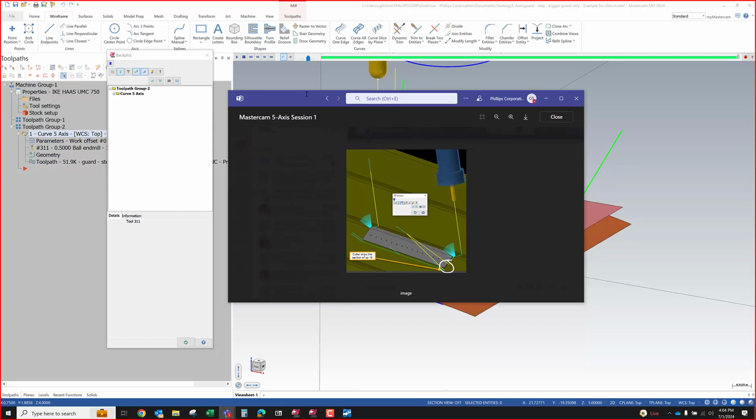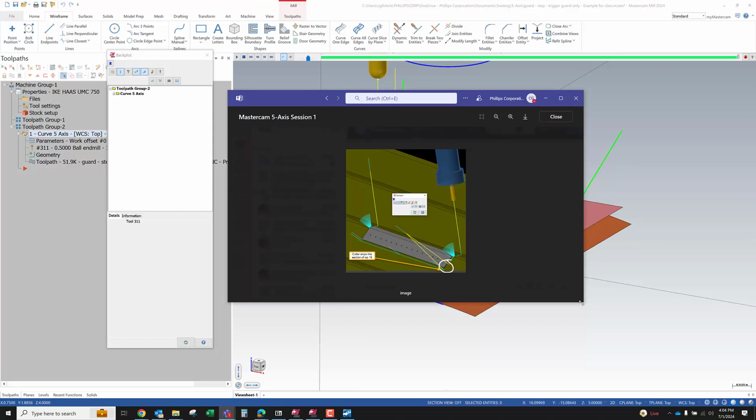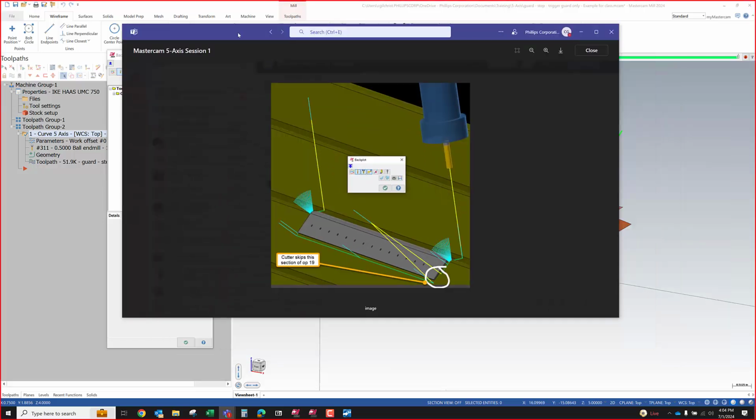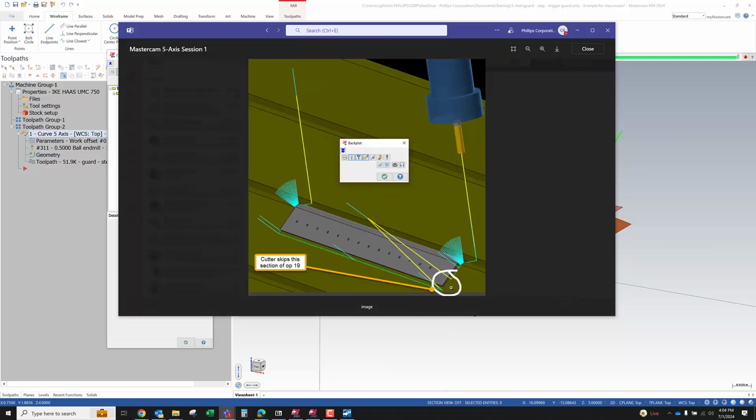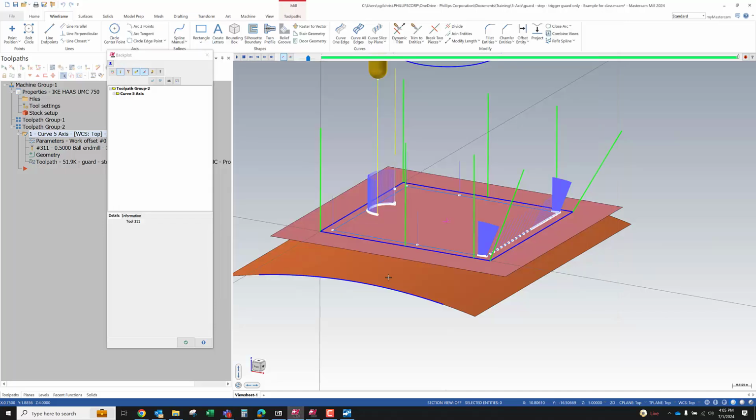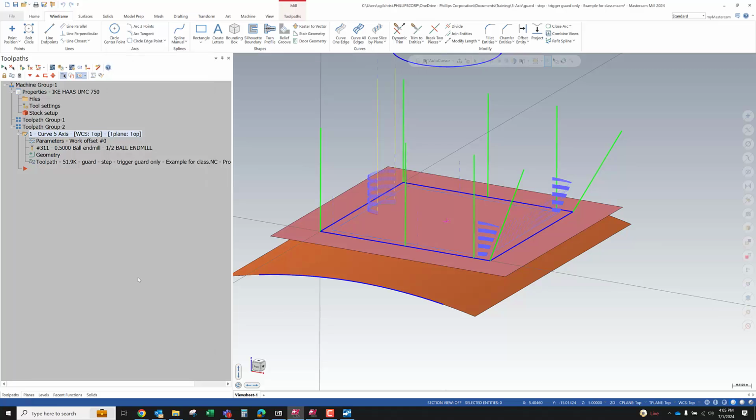I ended up having to reset the tool path parameters and then change the projection plane. Of course, you have to reset all the options and parameters within the tool path. And that fixed this problem. But I assume that this is probably related to a problem with the lines and arcs not touching the surface or being on the positive side of the surface. You guys see this?